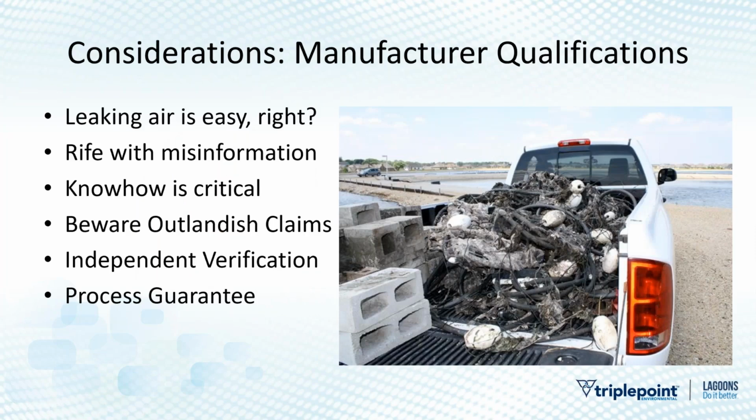Next, take a look at the manufacturer qualifications that you're dealing with. Unfortunately, in the lagoon space, you can get into some really unsophisticated technologies where you might have had a contractor who's installed a couple of aeration systems, and he's like, "Wait a minute, they're just leaking air out there. That's easy, right?" And anybody who just sat with me for the past 54 minutes realizes that aeration is a bit more complicated than just putting some bubbles in the water. I've seen lagoon systems where some manufacturer went out, bought bed frames, took bubble tubing like soaker hose that you get at Home Depot, and wove it in and out of the bed frame, and then dropped those in the lagoon, which worked wonderfully for all of a couple of days, but ended up breaking pretty quickly.